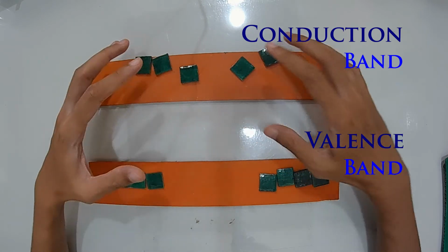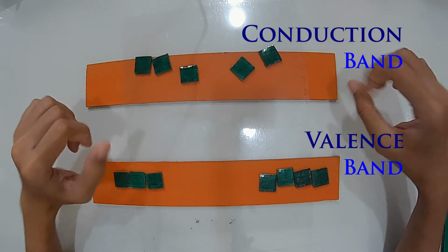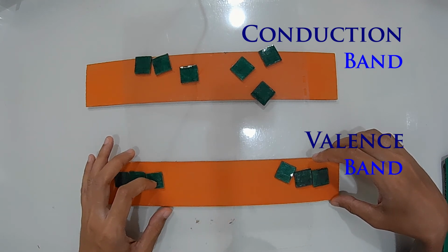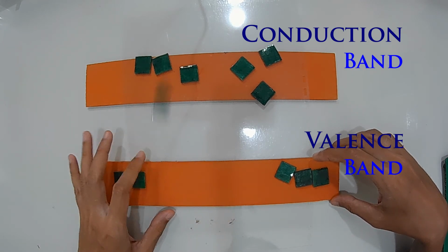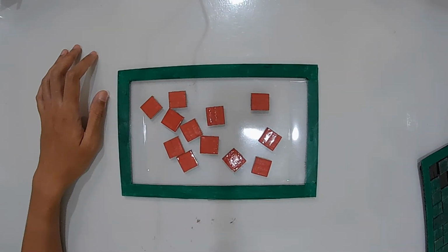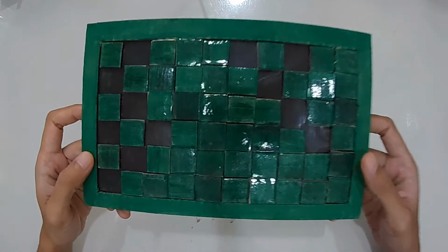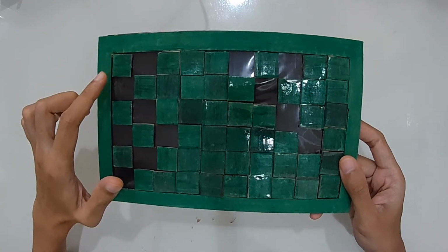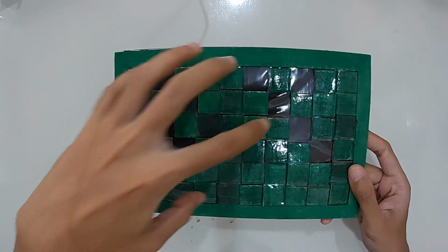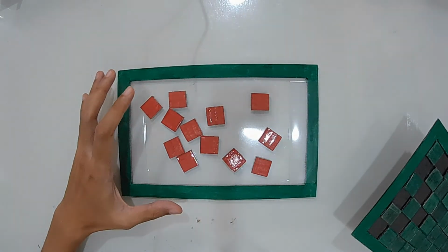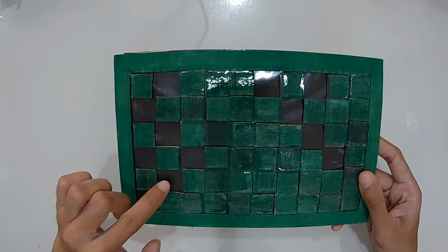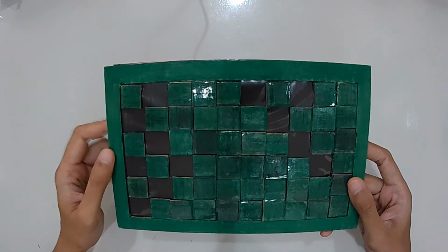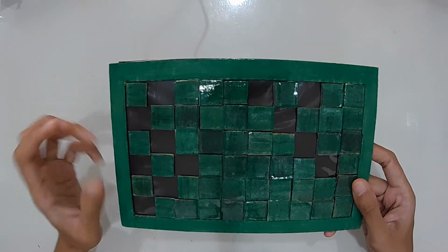The amount of heat we apply determines how many electrons jump into the conduction band and how much current can flow. When electrons become free, they leave their space here, as you can see, empty, because they leave their bonding and become free. And this emptiness here, the black color here, we call a hole, or lubang in Malay.